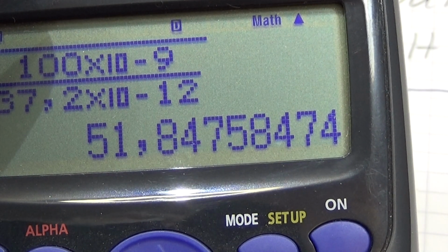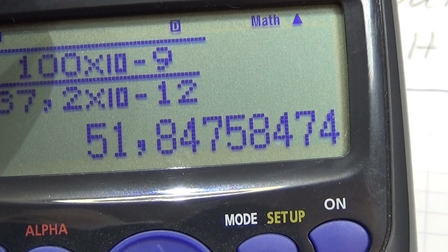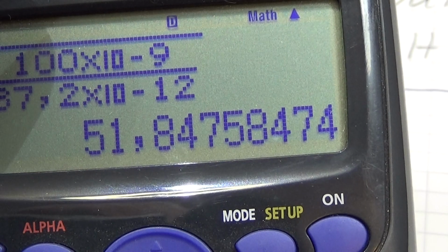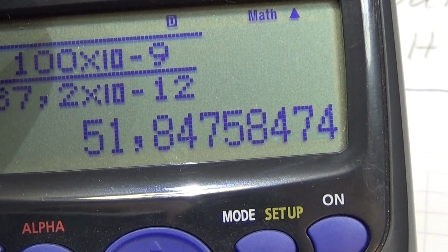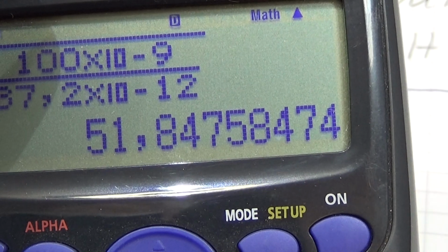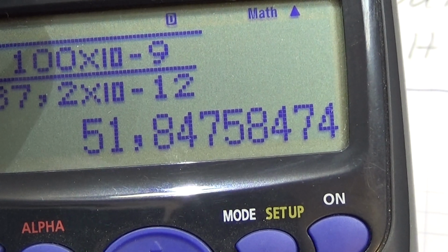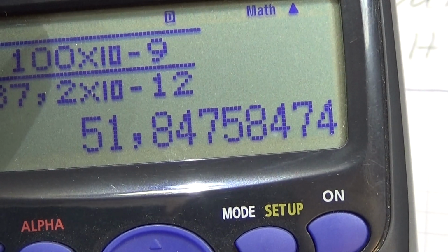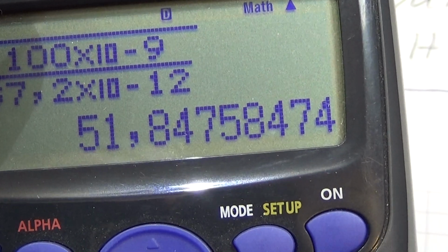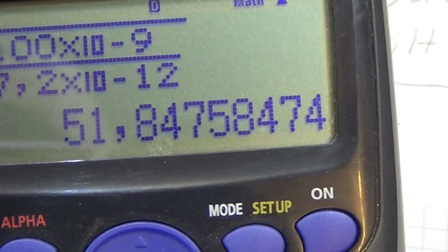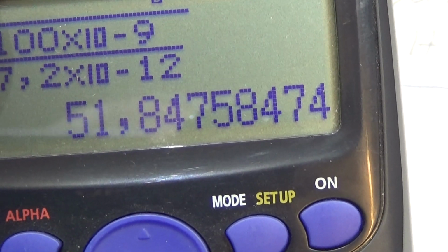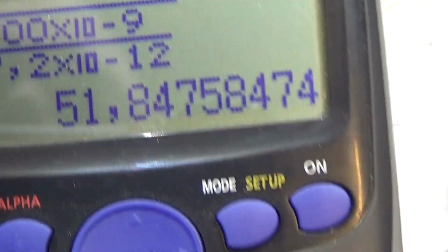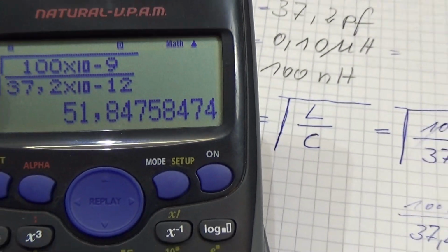So this LAN coax cable has 75 ohm, and as we already have heard, our coax cable for broadcast applications like your TV or your broadcast radio is using 75 ohm as well. So that is where you really need this most, to distinguish a 75 ohm cable from a 50 ohm cable. And now let's prove that this really works.